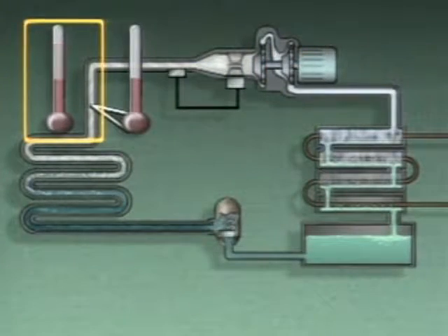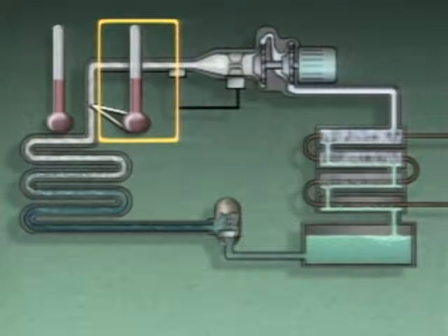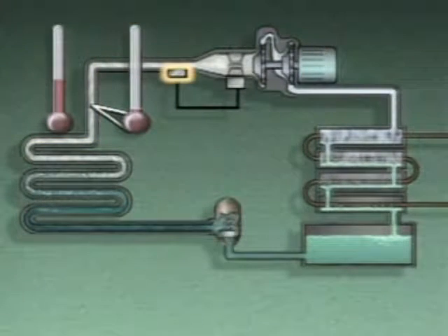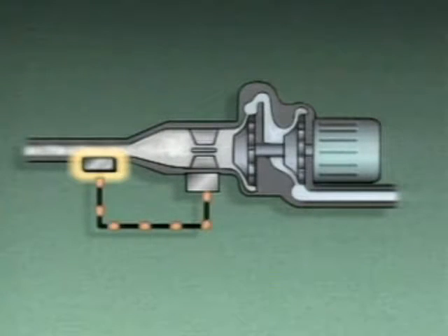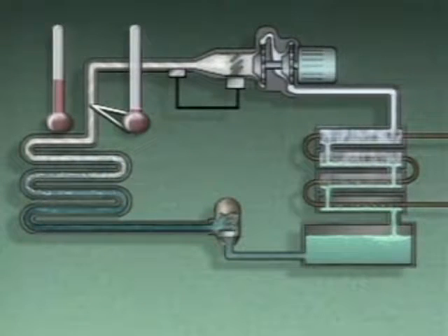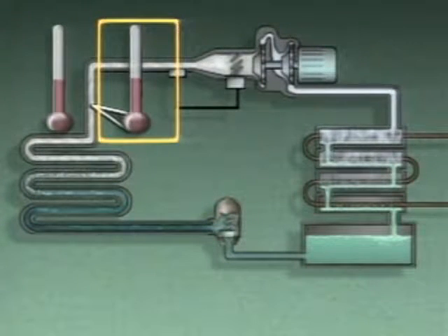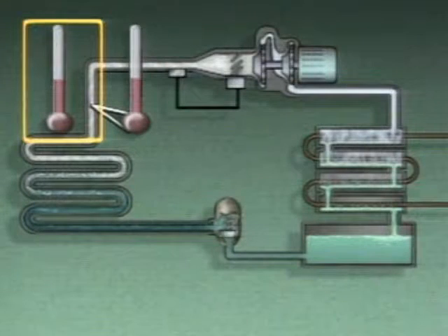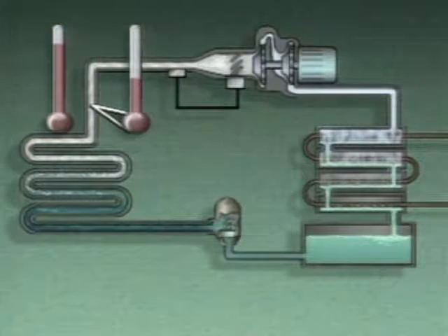value. Another way that refrigerant flow can be controlled in refrigeration systems that have centrifugal compressors is by using dampers or vanes. These devices are often located in the compressor suction line. When the temperature of the substance being cooled is too low, the temperature of the refrigerant flowing to the compressor drops. The dropping temperature is sensed by a temperature sensor, which sends a signal to close the vanes slightly. This reduces the amount of refrigerant that enters the compressor, so the flow of refrigerant decreases. The reduction in flow will cause the refrigerant in the evaporator to be warmer. This causes the temperature of the substance around the evaporator to increase back to its desired value.